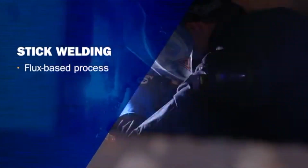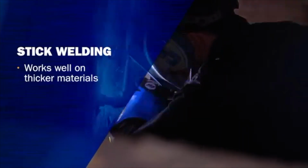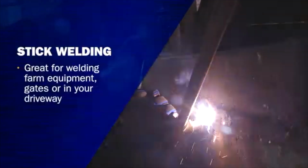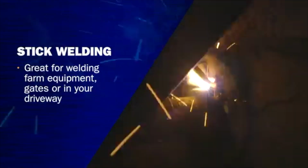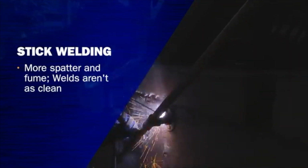Stick welding, because it is a flux-based process, works awesome outside. Wind doesn't affect it as much, and it can also work on thicker metals really well. Another advantage is that if your metal is dirty, if you're working on farm equipment or on a gate or even in your driveway, rust and debris don't affect it as much as the other processes. A few of the disadvantages of stick welding are that you're going to have a lot of spatter, vapor, off-gassing, and fumes, so it's not something you want to do indoors too much. Also, if you're working on automotive frame mounts, it's not the prettiest or cleanest weld. Usually when you're working on some sort of frame, you're either going to pick MIG or TIG.